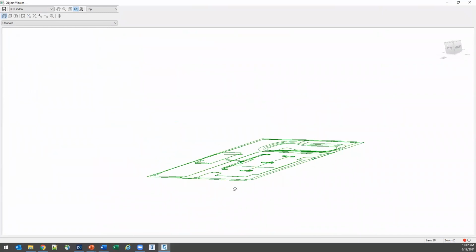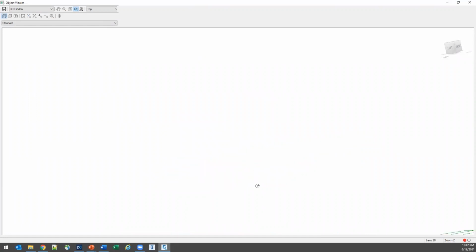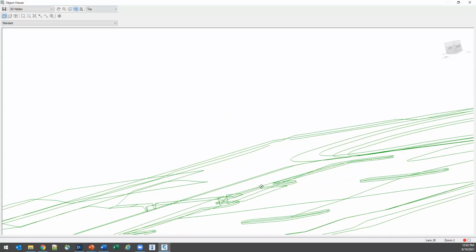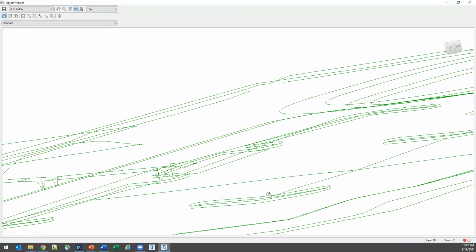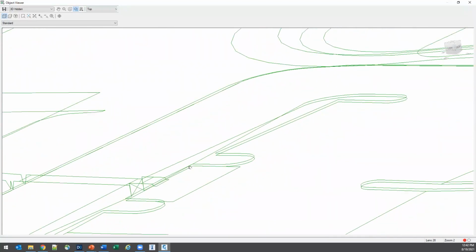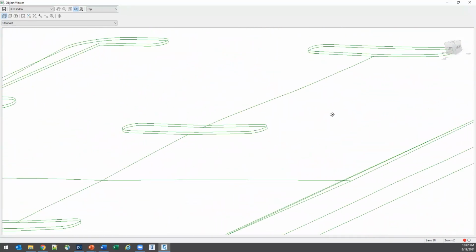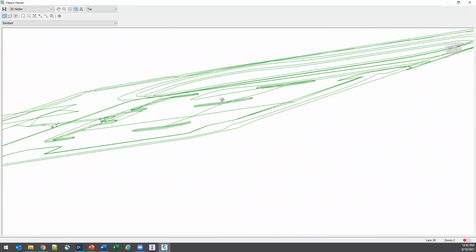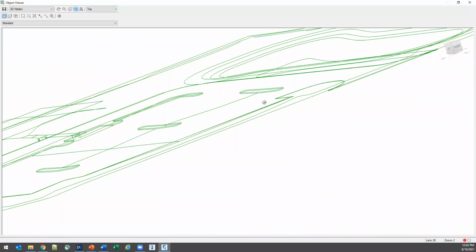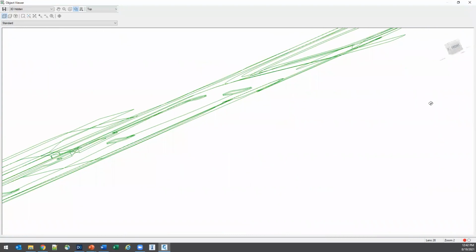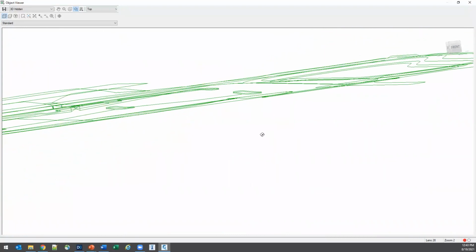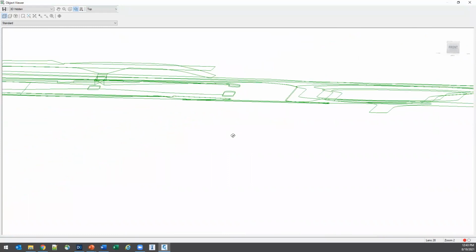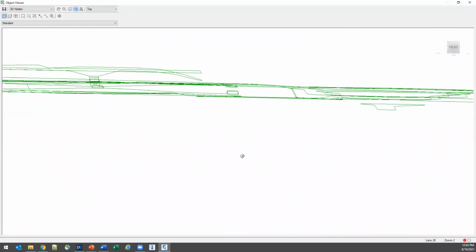So I've definitely got the elevation coming in there. I can see how my curbs are being put together without the surface. It's a little more difficult to tell, but I've got my gutter line, I've got my top back. I can see some of the slope happening; here's my low point. This curb is a little bit higher than the rest. Object Viewer is definitely more of an art than a science. So it can be a little tough to check it out, but you should be seeing your rough shapes in here.